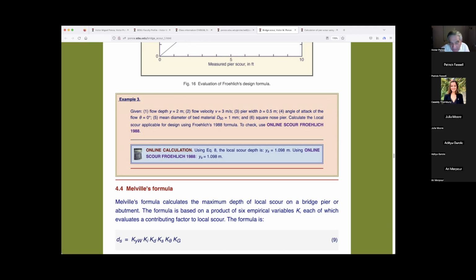That is unlucky. Why do we choose 500 years? Why don't we choose forever? Impossible. That's too costly. I already explained that. It used to be 100 years, but we had so many failures, particularly scour failures, that it was increased. Maybe 5-10 years ago, it was increased to 500. And now 500 is the norm. I think that's been said in the manual. So it depends. Now you could go to 1,000. You could go to 1,000 as a designer, but that has to be a conversation between you and the owner.